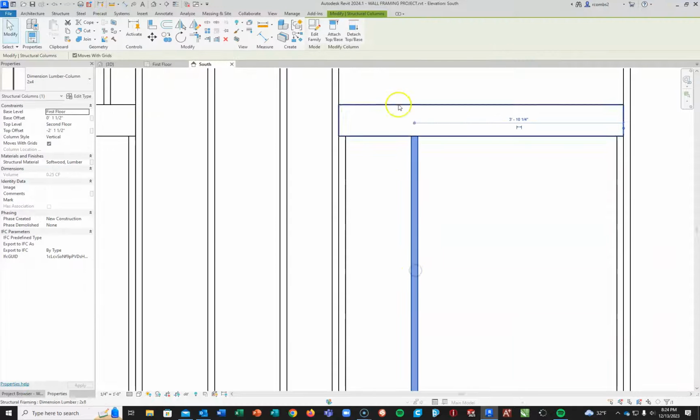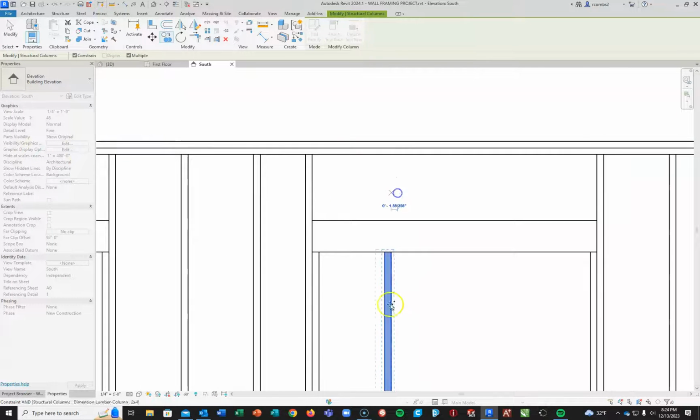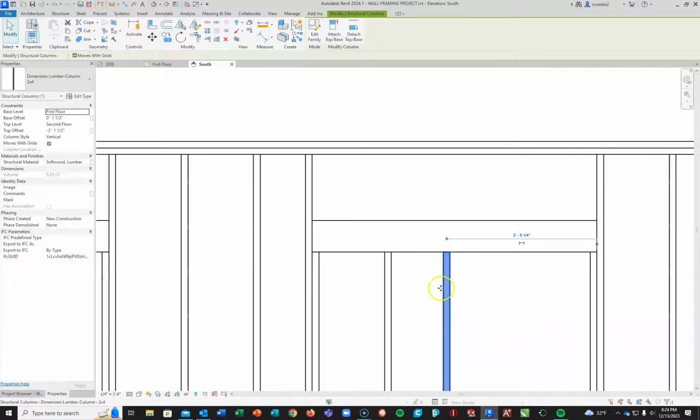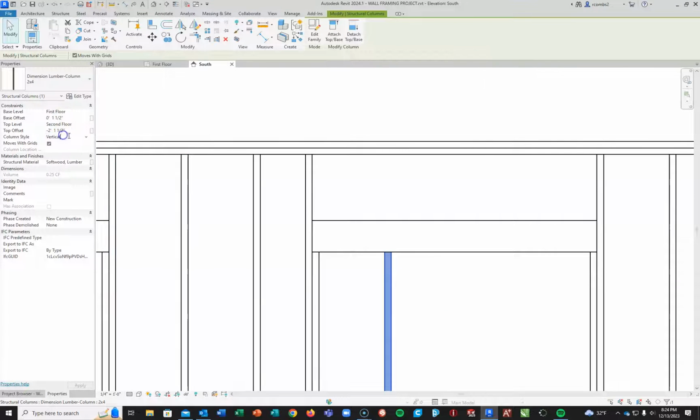Now I'm going to set this one where the top offset is -3 inches. That extends it up. Whoops, maybe not. I wasn't out of my tool. Delete that. Click on this one again. Top offset, -3 inches. Again, 3 inches is 1.5 plus 1.5. Okay. And then we go to the bottom offset and make that 7 feet 7.25 inches.